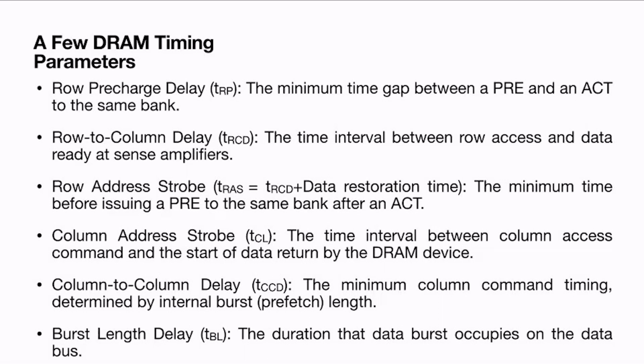And if I issue a pre-command, right? So if I issue an ACT command to read the data from a selected row, at what time can I give a pre-command? Let us say I opened row 1 and now I want to open row 0. How much time do I have to wait? That means before opening row 0, I have to perform a pre-charge operation. That is what we considered in the previous example.